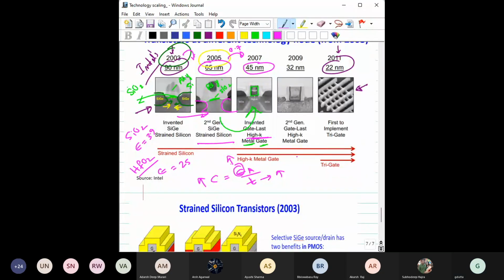Okay. See this gate capacitance. It is epsilon A by thickness. Say the area is the same, so we will remove the area. So it is basically epsilon by T. Now for silicon, it is 3.9 and say T is 1. Now we'll try to retain this value only. Here we have hafnium oxide, which is 25, around 4 to 5 times more, so suppose we make T like 5.